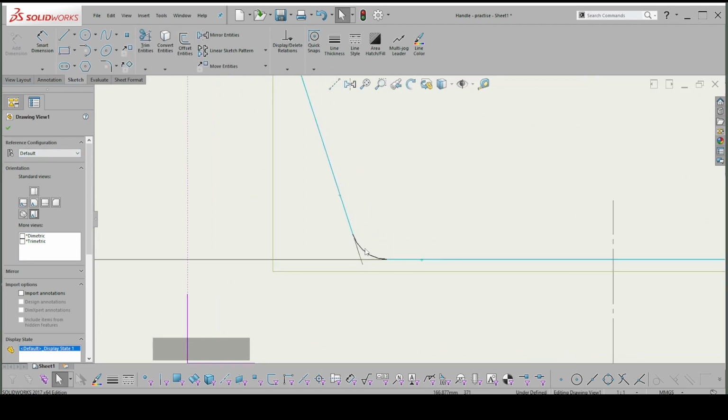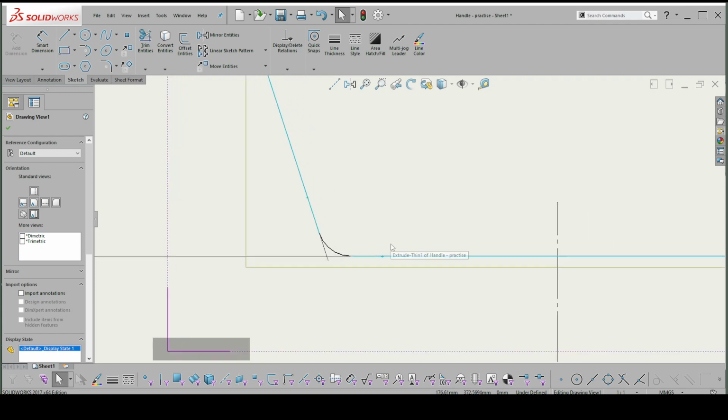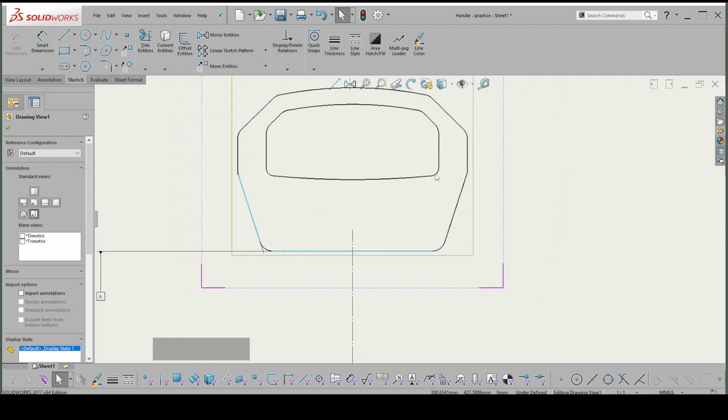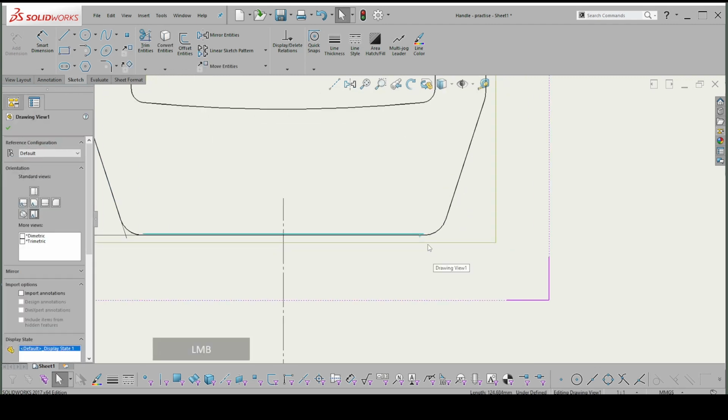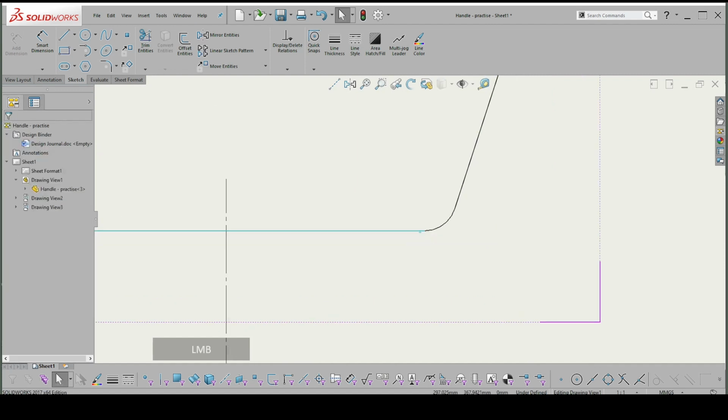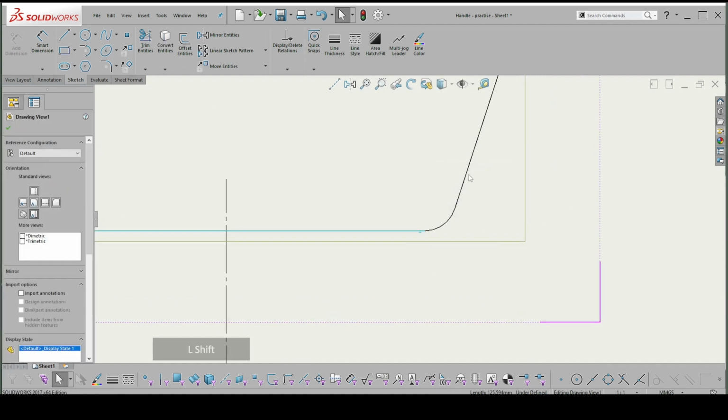Okay, so virtual sharp is a way of ignoring the fillets. That's really what you want to do in this whole drawing. You want to say wherever I see a fillet, a fillet is defined as something which joins one line with another using a radius of some sort. So wherever I see a fillet, I need to ignore it, and I need to go and put back the lines, the intersections that would usually occur if the fillet weren't there.